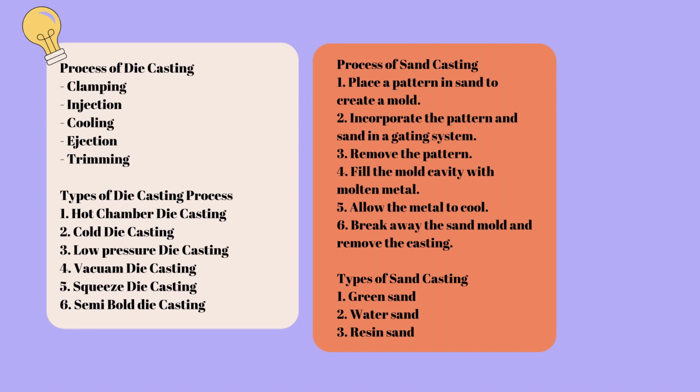For sand casting, the advantages are that the production is low cost. The second one is short lead time, high complexity shapes, and also a simple production process.